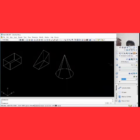Now we are trying to choose a cone that has an elliptical base. So we'll choose the cone command again. Now we have options here. So let's choose elliptical. Then it means we are going to type E, enter, and then specify the center, the endpoint of the first axis, and then specify the other point. You know your ellipse is different from your circle. Now look at it. This is the other endpoint.